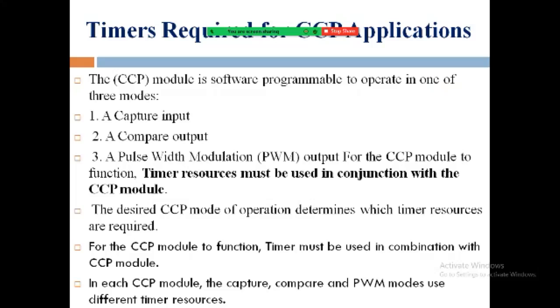For the CCP module to function, timer resources must be used in conjunction with the CCP module. The desired CCP mode of operation determines which timer resources are required. In each CCP module, the capture, compare and PWM modes use different timer resources.